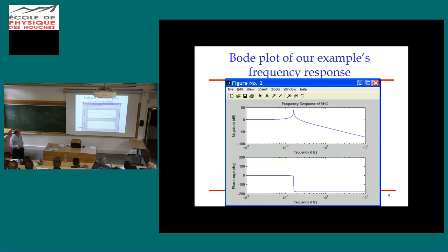Okay, so there are a number of things we can see. There is a peak. There is a particular frequency at which the system responds much more than anything else. And remember, this is a log scale, and okay, that's 40 dB, or a factor of 100 amplification on resonance. What else do we see? For all frequencies below the resonance, in the limit that you get far below the resonance, the frequency response is constant, and in particular, this frequency response has unit magnitude.